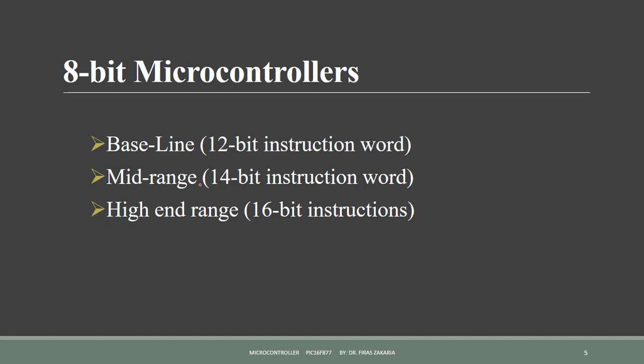We have the baseline family, which uses 12-bit instruction words, and we have high-end range family, which uses 16-bit words. So the PIC16F877 belongs to the mid-range family and it uses 14-bit words. We will limit ourselves to the mid-range family, knowing that if you have it all figured out, you will move very easily to another family and even to another microcontroller.